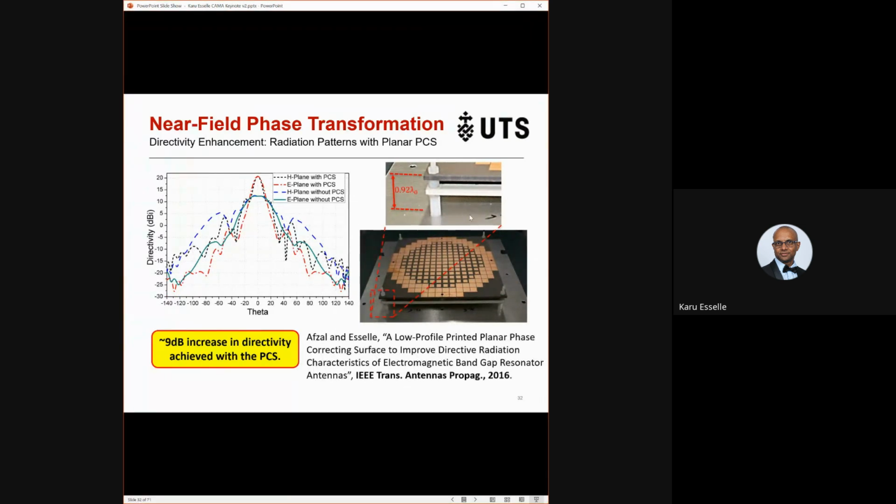Now this is the printed one, metasurface, a printed planar circuit board, and you can see how thin it is. This is a multi-layer printed circuit board. I think 3 layers of metal and 2 layers of dielectric, but very, very thin. And that mimics that bulky prism, bulky lens. So this is all you need.